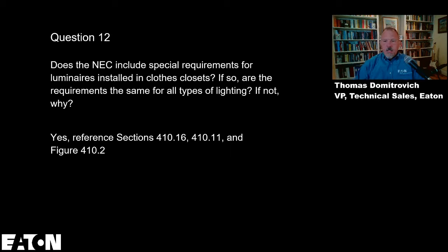Looks like the main 410.16 content and 410.2 definition correlates to the title. Yes, that's exactly right, Brian, that's what they did, they correlated that. So Don Gannier pointed out a closet for towels would present the same hazard if there are storage shelves close to the location of the luminaire. And Don, I agree with you 100% that you are presented with the same hazard, but even what they changed didn't change our requirements, because we have specific requirements for closed closets in 410.16.